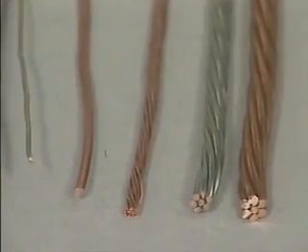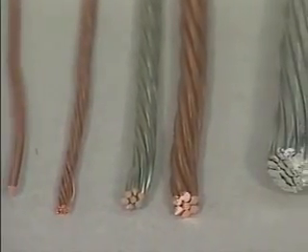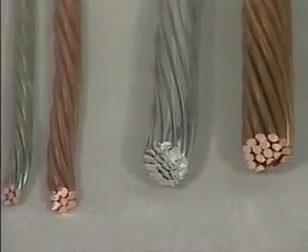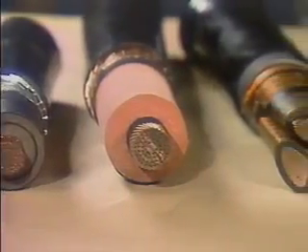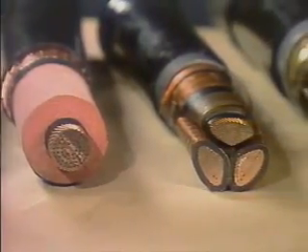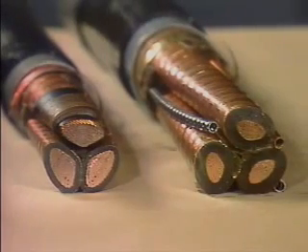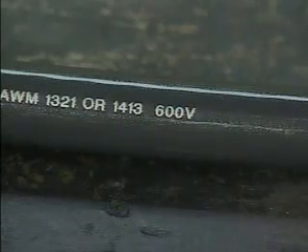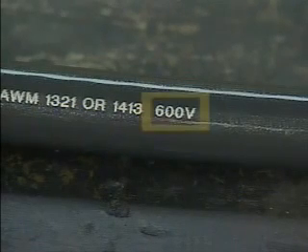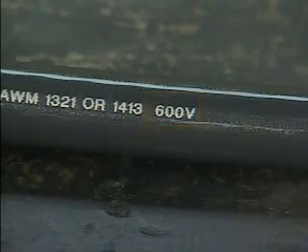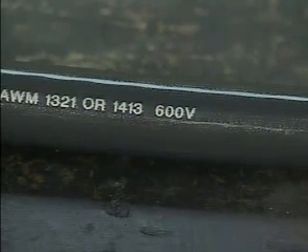The conductors that we've discussed so far are typical low-voltage conductors. That is, conductors that are built to handle up to about 2,000 volts. Conductors that are built to handle over 2,000 volts are constructed differently. That's because they rely on design factors in addition to the thickness of the insulation to handle high voltages. In this unit, we'll focus on low-voltage conductors. That is, on conductors that are designed to carry less than 2,000 volts. Take a minute now to try a question about conductor construction.